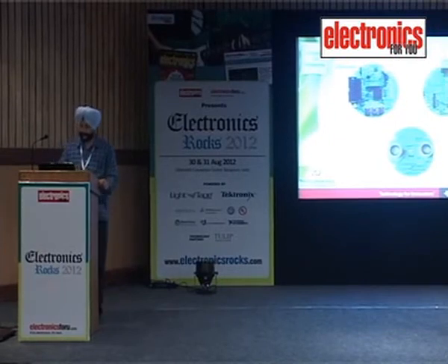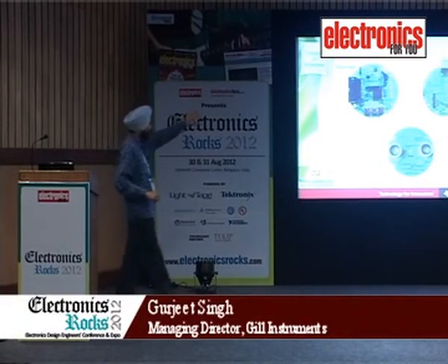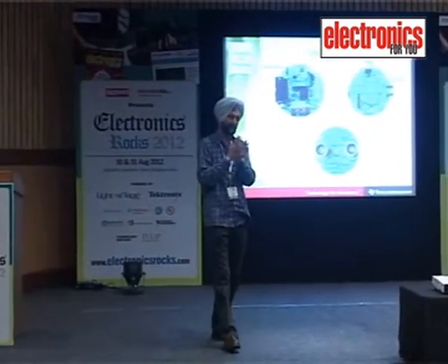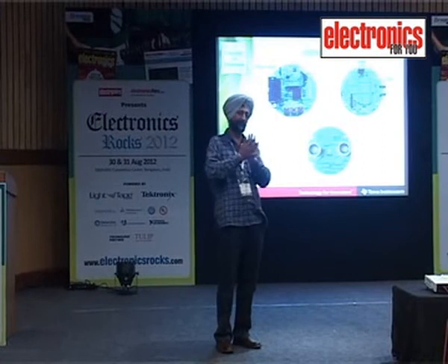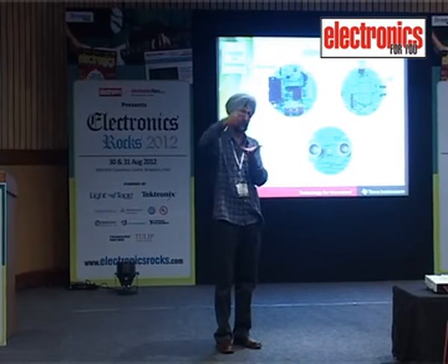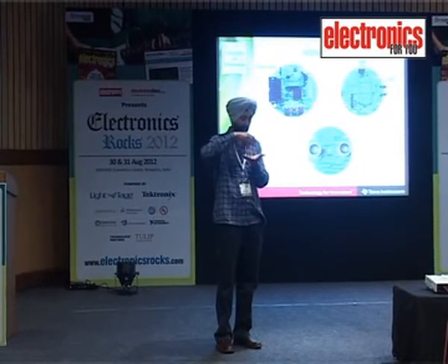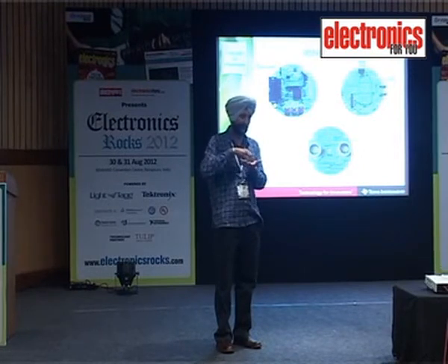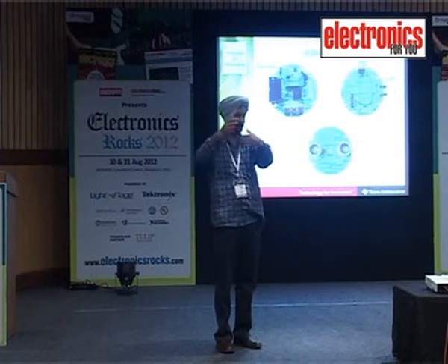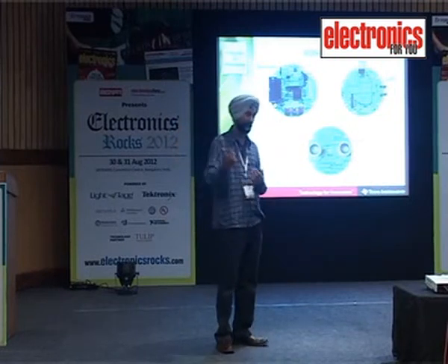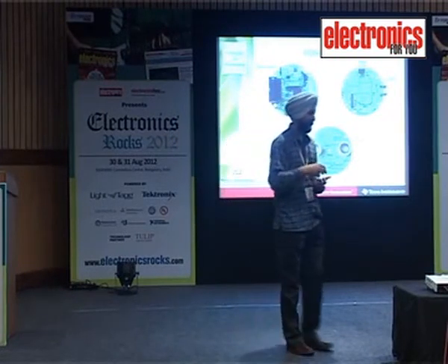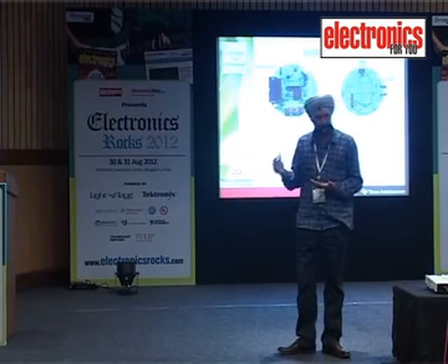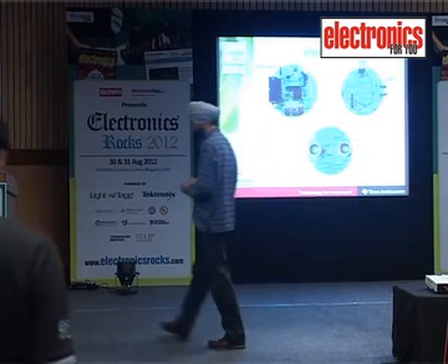And we have gateways based on these boards, you can sandwich. These are piggyback boards. So once you make a sandwich of these 2 boards, you will have short range wireless, plus you will have GSM connectivity. So that's for the last mile connectivity. Let's say you are collecting information from multiple sensors, maybe in the forest or maybe in patients. Ultimately you need a long range connectivity where it will get connected with the server. It will start pushing the information to the servers.